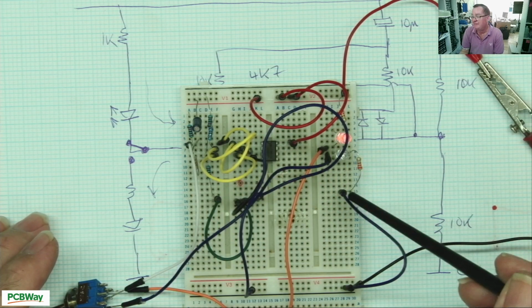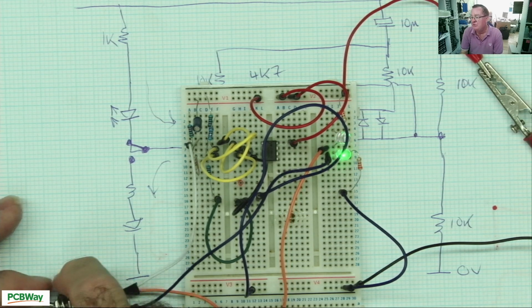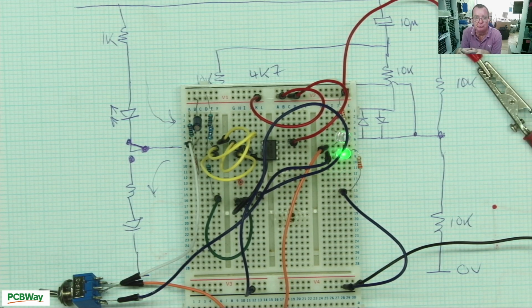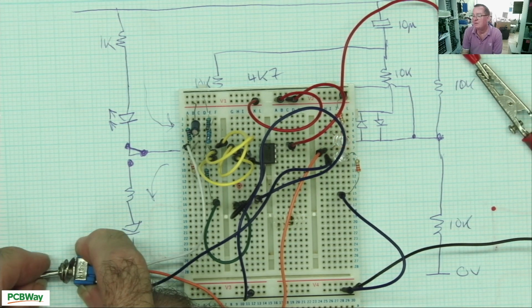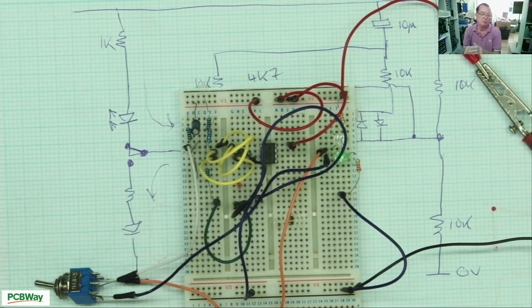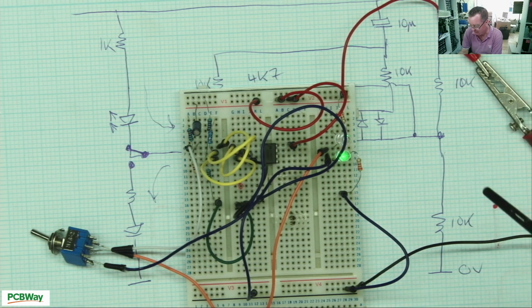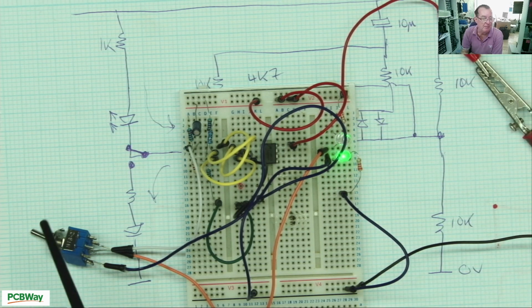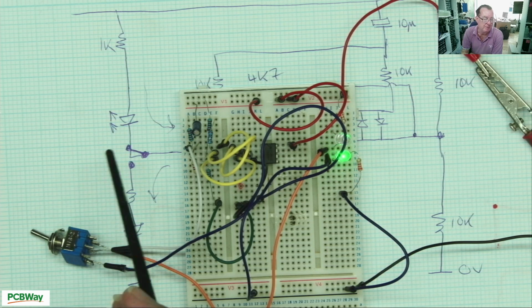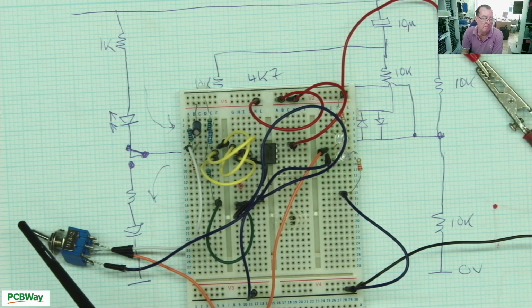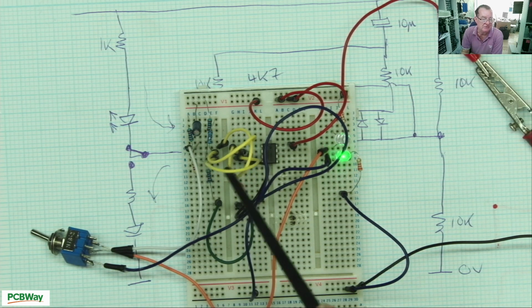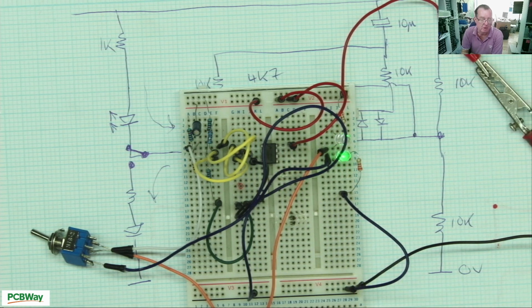Leave the other LED and resistor in, and then we can test whether an op amp, which should be able to, can both sink current and source current, because you could have a fault situation where it only works in one way but not the other. So I think it's advantageous to actually leave the switch in and the additional LED and resistor. And then we can, if we want to, label this as comparators or op amps, or I would probably label it as sink or source. So it either is sinking current into the op amp, or it's sourcing current from the op amp or comparator.